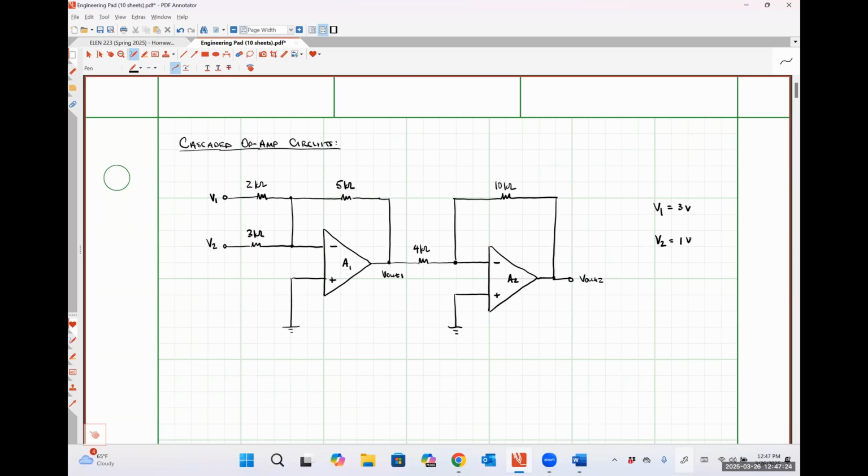And then you could feed the output of that comparator into an integrator because a square wave integrated looks like a triangular wave. So you can do signal processing that way. But it's all about just performing multiple mathematical operations in a specific sequence. Okay.